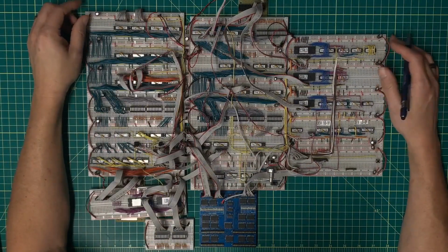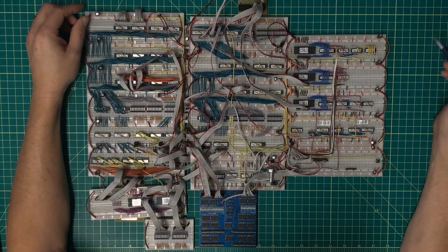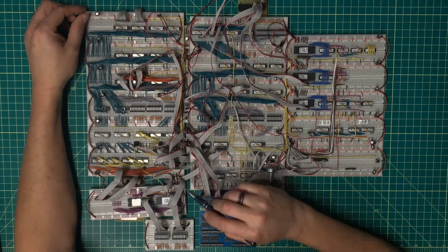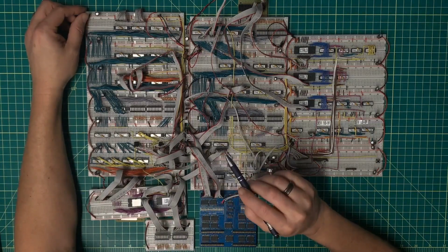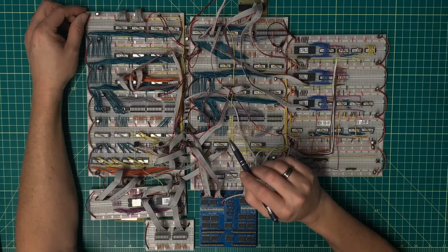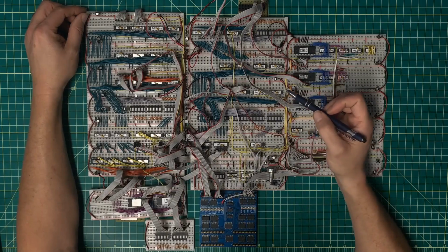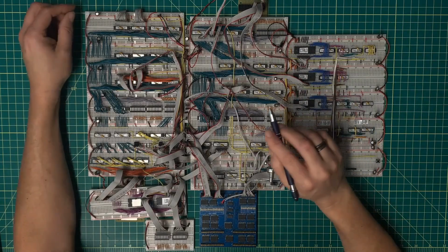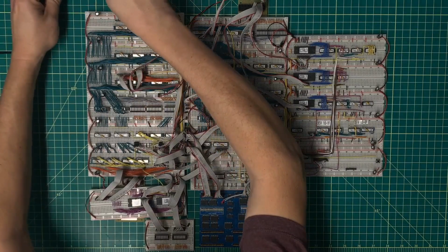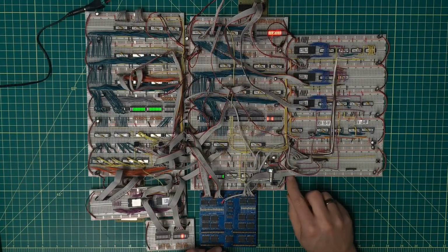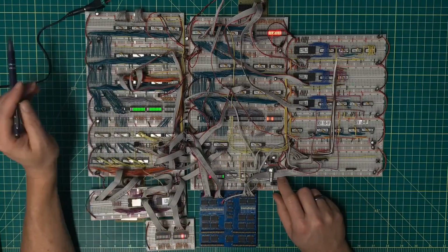Okay, I've zoomed quite a ways back out again so you can see everything. I still have in my program ROMs the latest jump test that I did from video 51. And that is the test that confirms that the jump instruction is actually properly flushing the fetch register and fetching the correct instruction after the jump. So that said, let's get this plugged in and let's step through this code real quick and make sure that when I do load an instruction, it actually suppresses properly here.